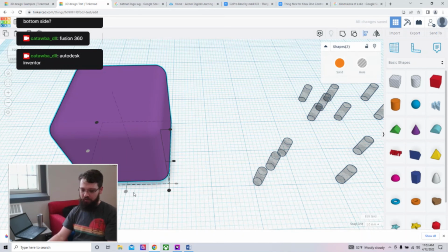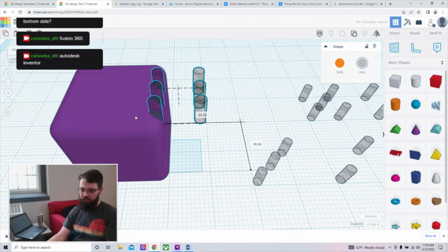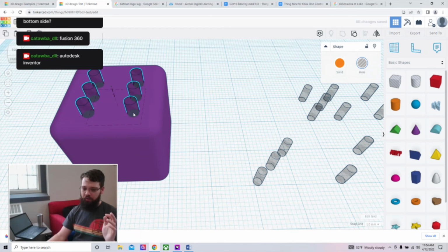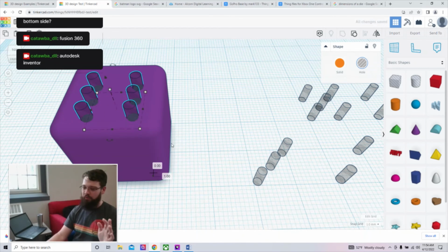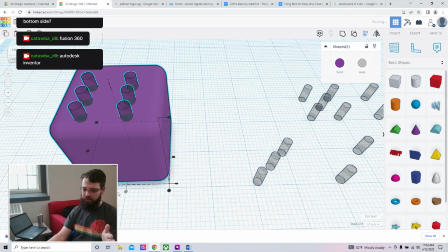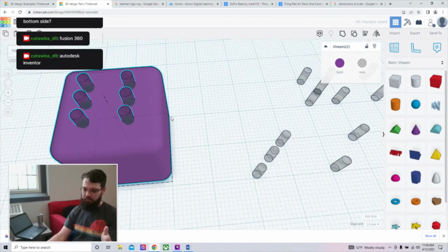And I can click this dot and I'll center it in the middle this way. You know what I really should have done is I should have done this. I'm going to float this thing up in the air so that you can see it. There. I'm going to offset it. So that's what I was going to do. Highlight both of them. Align. Click the middle one here. You see that it snaps aligned here, and click the middle one there. It snaps that way. And if I look at it, the thing is centered.